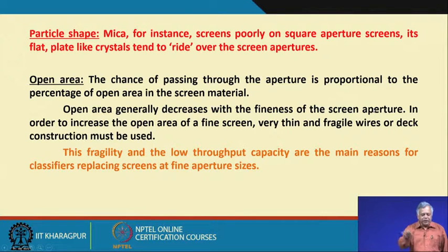Why? Because the material gets choked and blocks, since you have more near-size materials, and at very fine aperture sizes the fine particles are very difficult to pass through. So, they plug your openings.